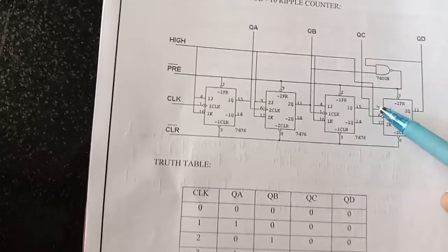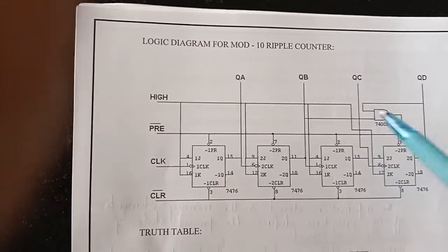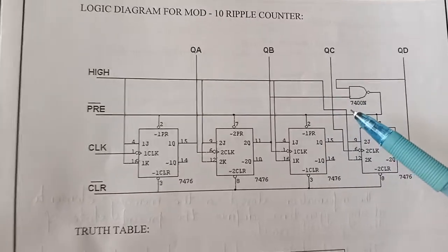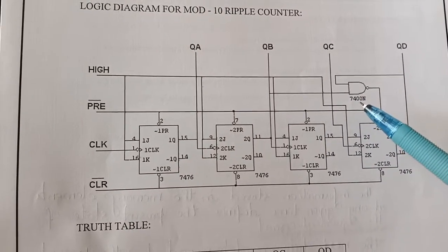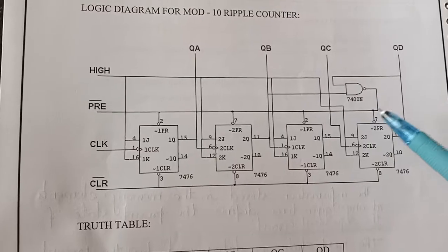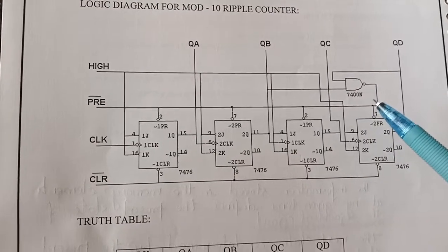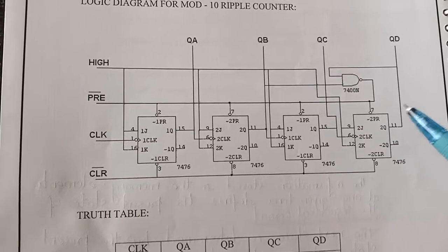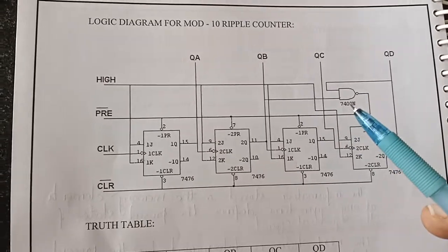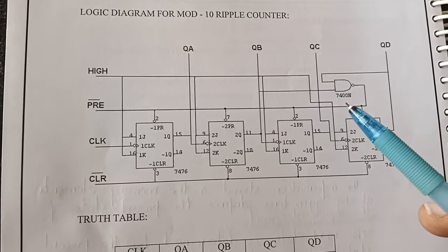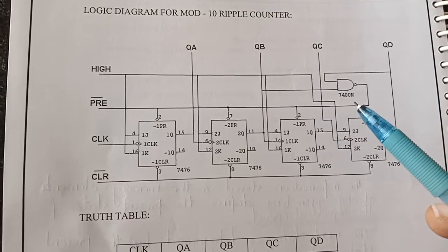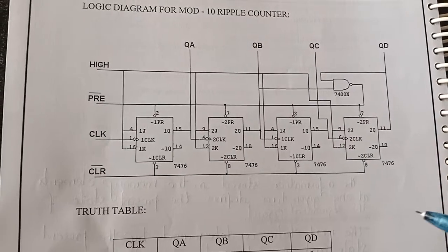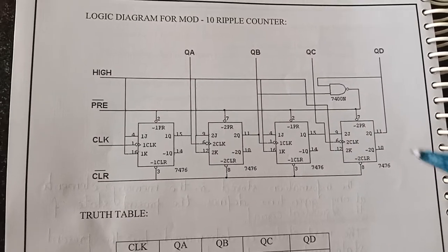So this is the connection diagram. Except for this part, the remaining connections are similar. Here we are using an additional 7400 NAND gate to limit the clock pulse count from 0 to 10. Because this is a Mod-10 counter, this combination stops the counting, allowing clock pulses 0 to 10 only, and for the remaining values the output is reset.